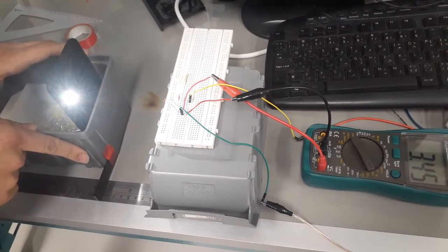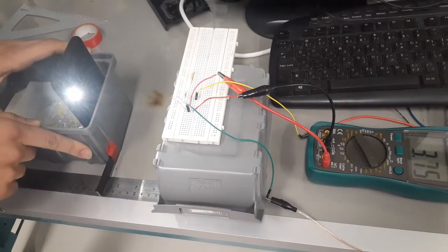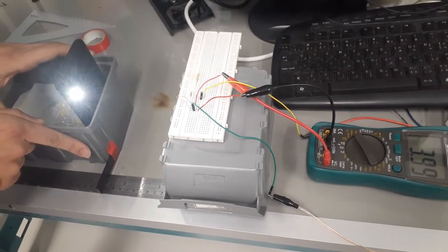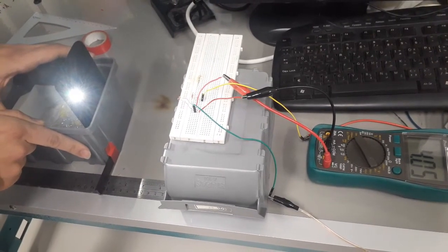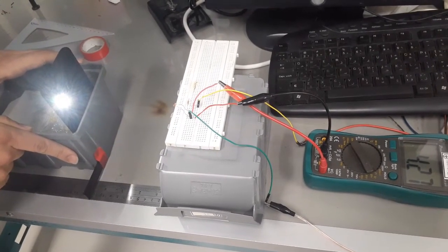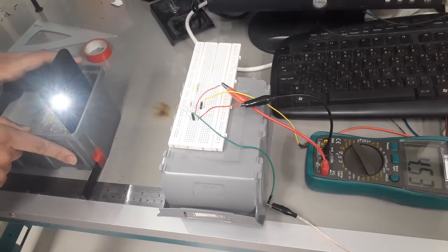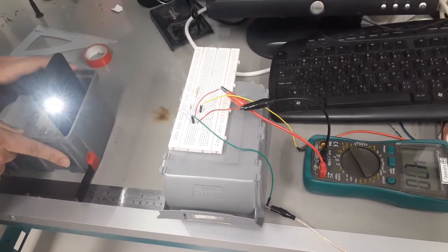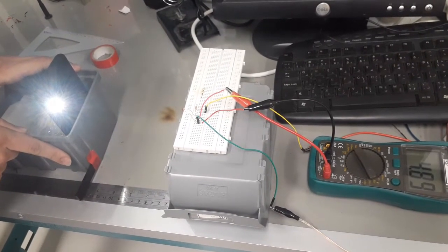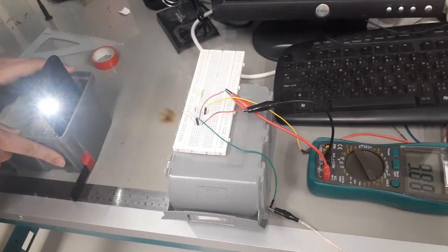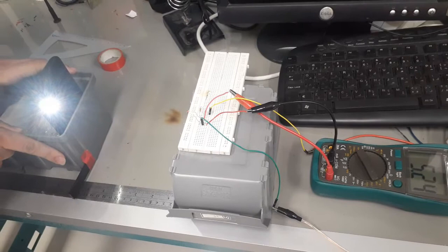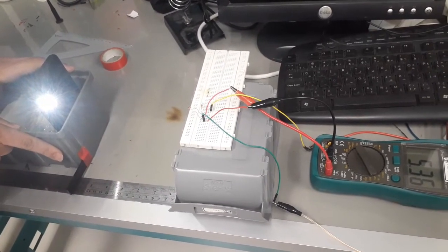We have to go steady and slowly in order not to disturb anything, in order not to corrupt any data. We have to keep the angle between the LDR and the flashlight fixed, and we have to wait after we put our flashlight at a fixed distance in order to measure a steady voltage value. That's why we wait after each centimeter for like 1 or 2 seconds.